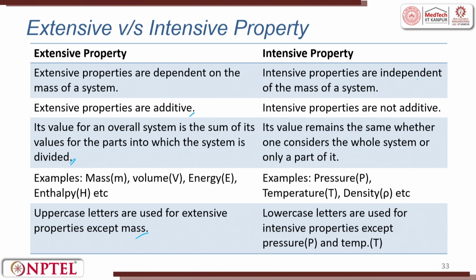When we go for intensive, these properties are independent of the mass of the system. These properties are not additive. So, here it is additive, here it is not additive. Its value remains the same whether one considers the whole system or only a part of the system. Please understand, these two properties are very, very important for you. So, you try to take a total container, inside you take 1 unit, it is the same. So, it remains the same whether one considers the whole system or only a part of the system. Pressure, temperature, density are part of it. Lowercase letters are used for intensive properties except pressure and temperature.